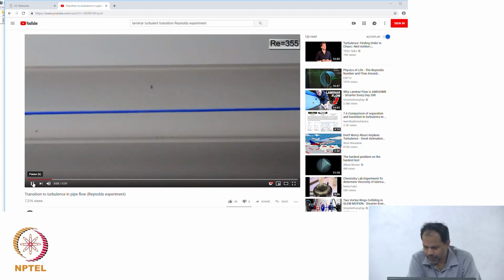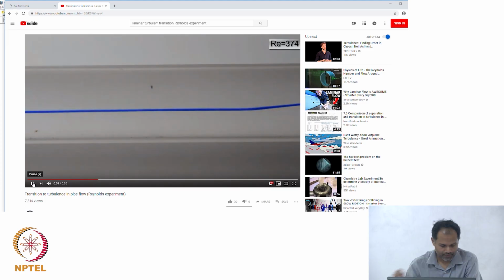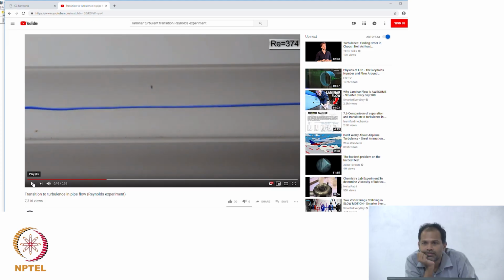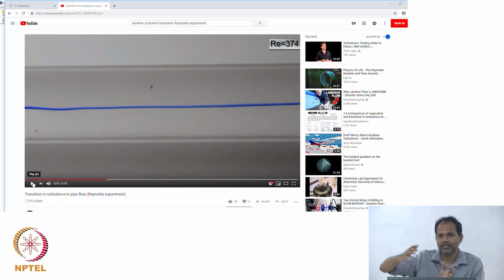It doesn't look like a pipe because the Reynolds number seems to be very small. Diffusion will happen, but diffusion is a very slow process, over a very large time scale. If there was no fluid flow, you would have seen the ink getting diffused, but you are not letting that happen. Your fluid flow is sufficiently bigger than that.